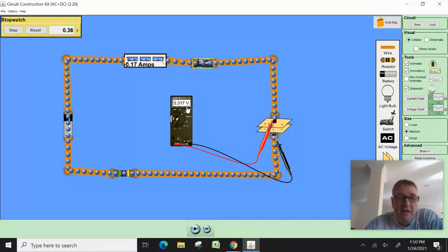I could have been click, click. You'll start to see the capacitor has started to charge. There's some charge built up on the upper plate, positive, and some negatives being driven off the battery to the bottom terminal, some electrons leaving, and leaving the top terminal, the top plate positive. You'll notice there is a little bit of charge built up, and therefore there's a little bit of voltage across the capacitor. Remember, this is 9 volts.